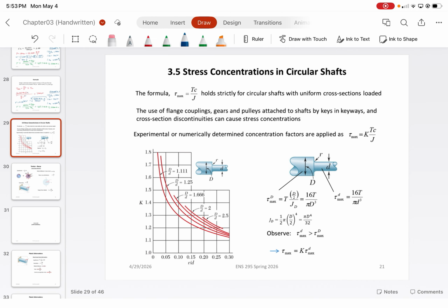All right. Another topic, stress concentrations in circular shafts. Guess what? They function the exact same way as all of the other stress concentration problems that we had previously dealt with. Just in this case now, it's just torque, all right? So the idea would be first to look at the table here for the given load and boundary conditions. Of course, these geometries will vary, depending.